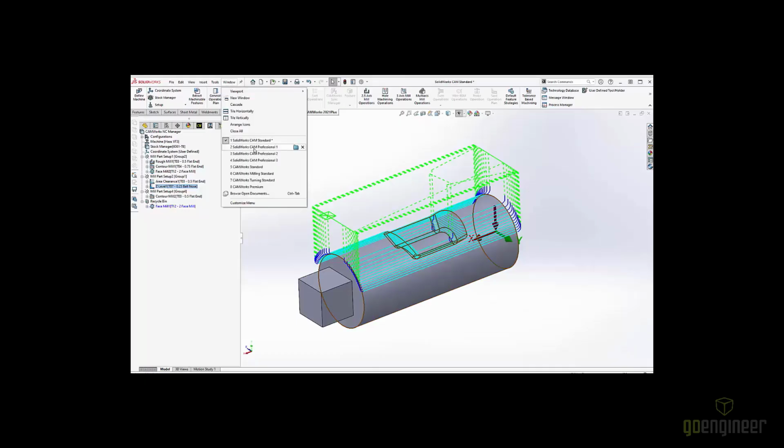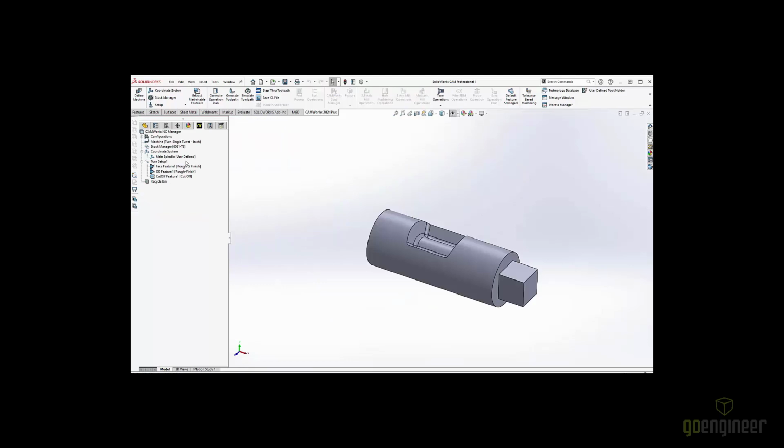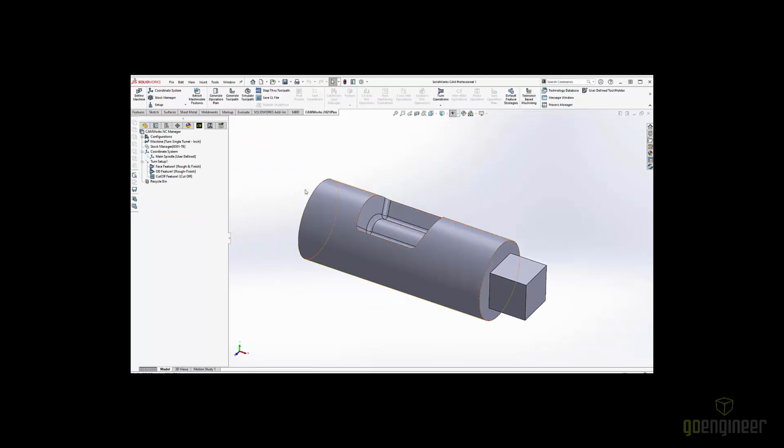Let's jump on to the next part here, SOLIDWORKS CAM Pro. So just talking about turning. Turning is, once again, something that happens very automatically, especially 2-axis turning. Automatic feature recognition, that ability to analyze our part and create our features for us. In fact, I'll go ahead and just delete this current setup I have, everything programmed, because with the ease of use of the software, I can get back there within a few seconds. I'm going to go ahead and extract machinable features.